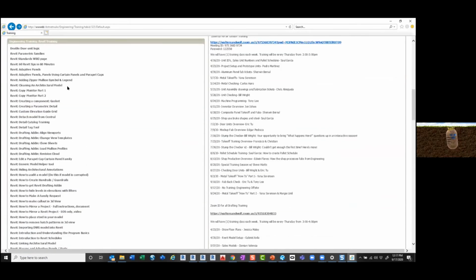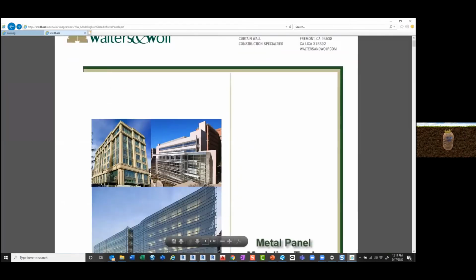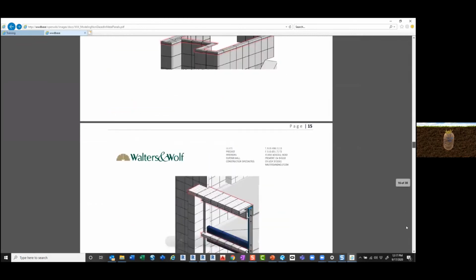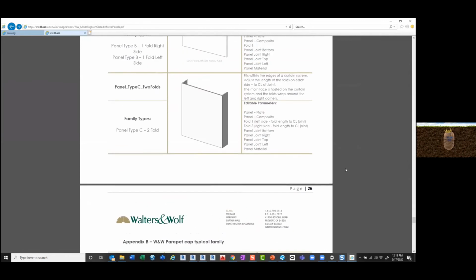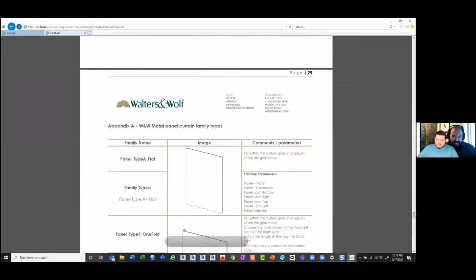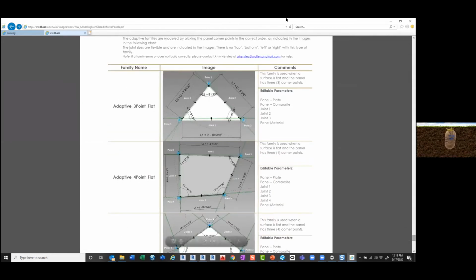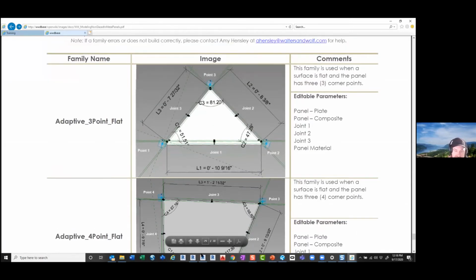Yeah, going to what Andrew said, it's pretty obvious in either the takeoff browser or in that Excel file when you're expecting a bunch of 2-fold panels and then you start getting 5-fold, 6-fold, and weird panels. Then some of the faces aren't painted so that they're ignored. Yeah, in the beginning, we were getting 24-point panels, and we're just like, what? Yeah, exactly. It's extremely critical that the faces are painted correctly. Otherwise, it's a lot of troubleshooting on our end.